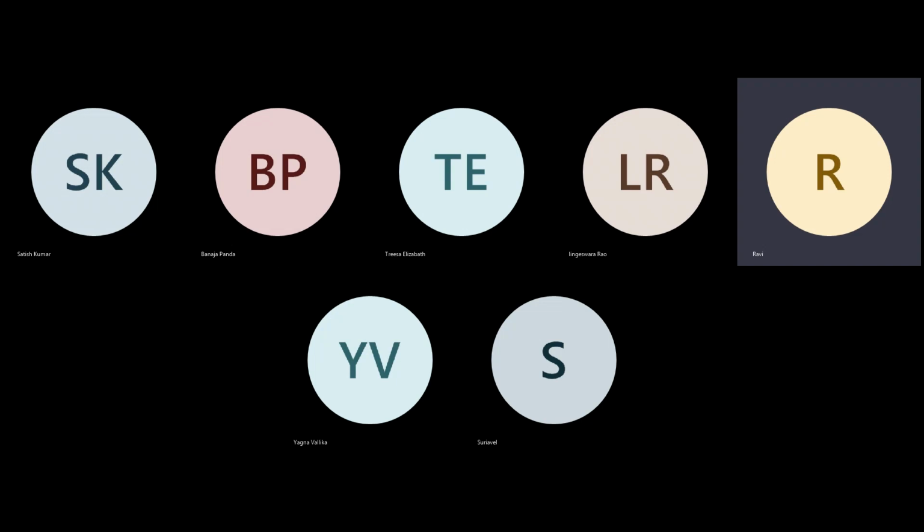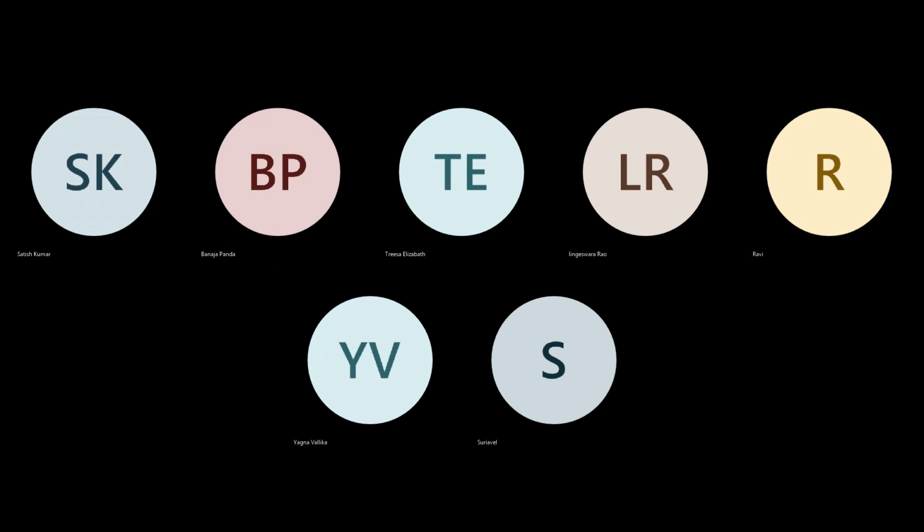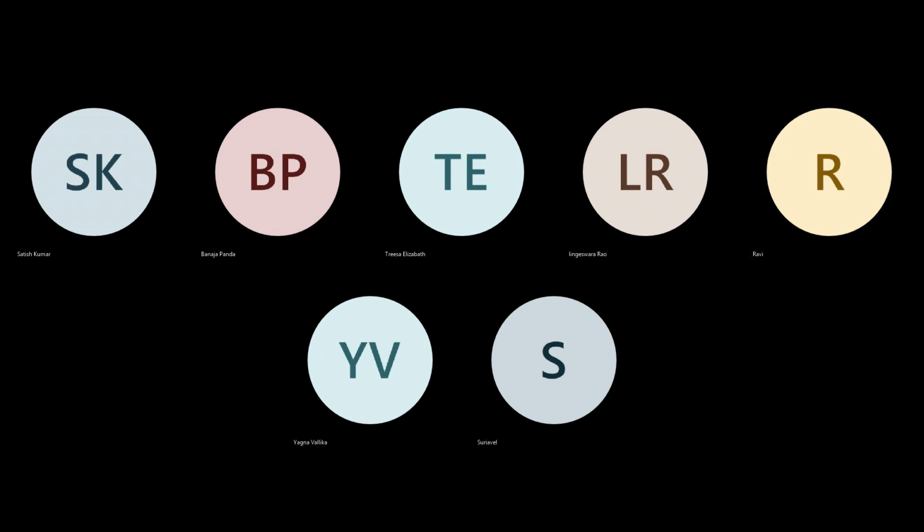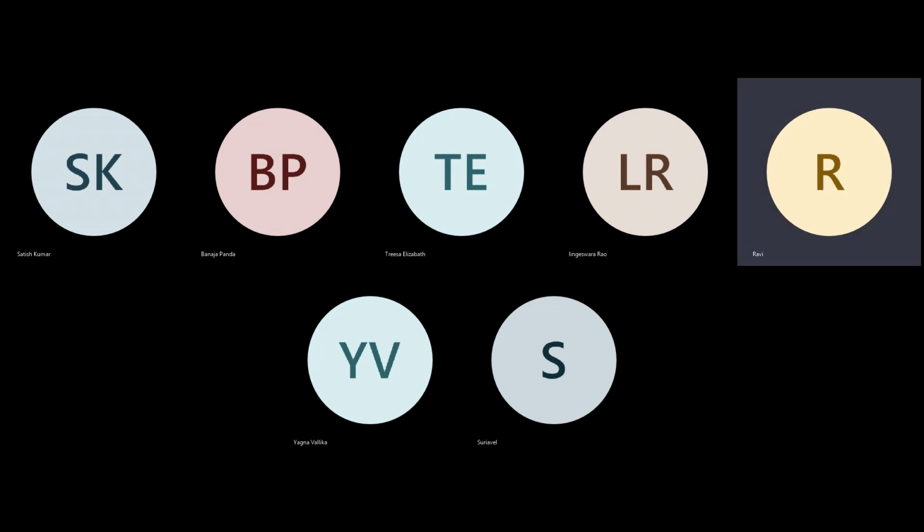We can choose the type of memory, because memories actually have multiple versions. In the floor plan, you have to understand the library has 3-4 different varieties. High density library means what? Less area. Sorry, high density means it occupies less area. It is an area-optimized cell.